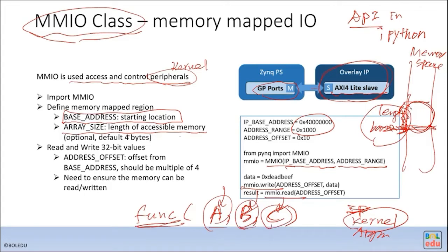These registers will be located in the AXI Lite range. When you synthesize and go through the Vitis flow, this information will appear in the block design, and I will explain that later. Eventually it goes to the API.